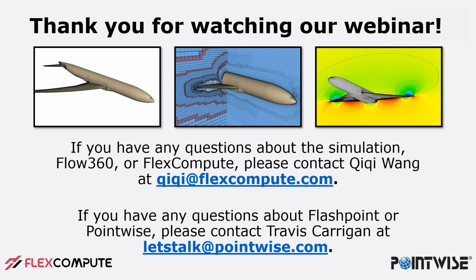But that's handled automatically. And if you have a long, slender surface that you believe should be mapped, but it's not, when you're still in the Flashpoint surface meshing tool, you can hover over the mesh on that thin surface, and it'll tell you why it didn't map it. It may just be because the mapped subdivision ratio needs to be adjusted, and that's over in the advanced tab, and you can use that to control that behavior. If it's not mapping, there could be a variety of reasons. Perhaps there are more than 4 curves, or it's broken up into more pieces, that kind of thing.